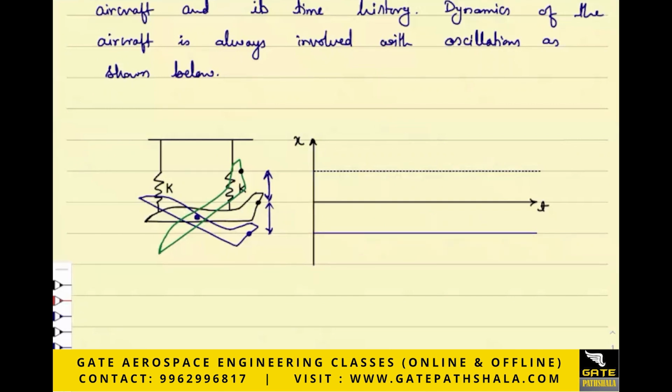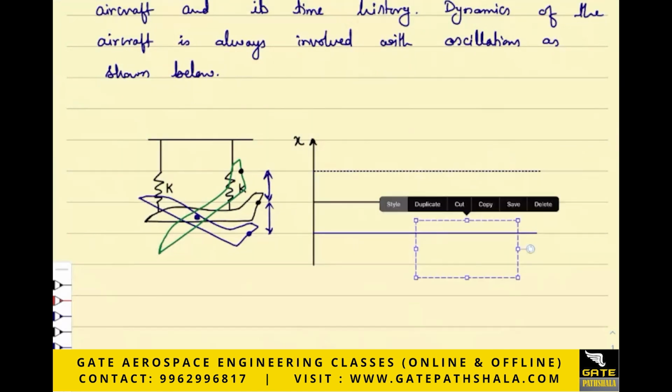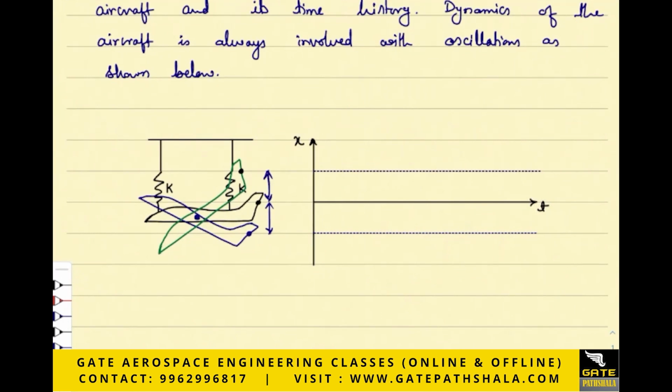Okay, after that much displacement here, now it is left for the response of the aircraft. So this aircraft will try to come back to the equilibrium after getting displaced. Okay, it will move towards the equilibrium and it will overshoot the equilibrium position. In the first cycle you will see that the amplitude of oscillation was this big, same as this x naught.